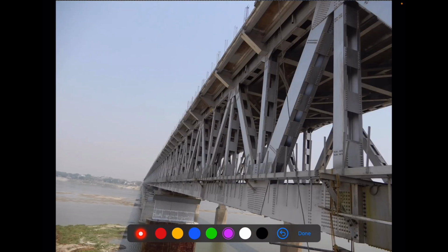Yes. So here you can see the top arrangement. This is a sway girder kind of arrangement. This is top lateral bracing, and sway bracings have not been provided because, by virtue of having a deck slab, it is already a rigid, much more stable structure.